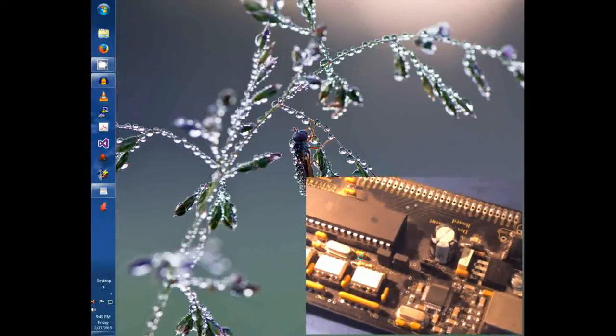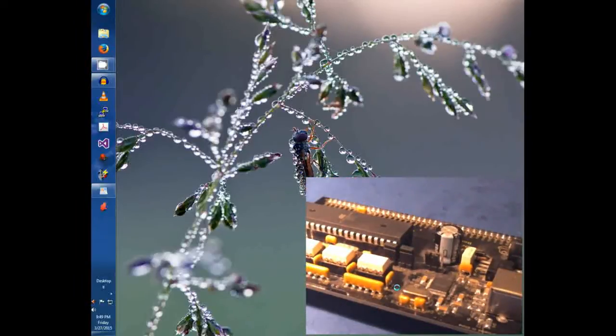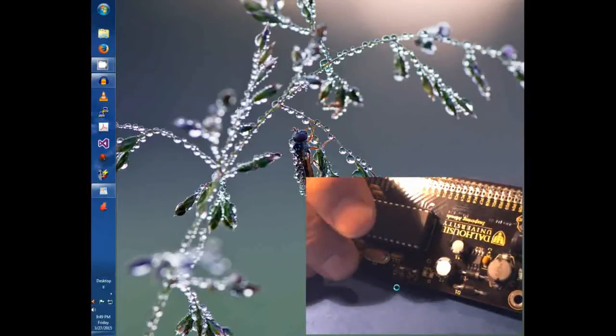On the older boards, simply insert the jumpers on the RxD and the TXD jumper pins. For the newer style boards, the jumpers have been replaced with small solder jumpers as shown here. Simply put a bead of solder on each of them, and that will connect the TXD and RxD pins to the USART pins on the microcontroller.